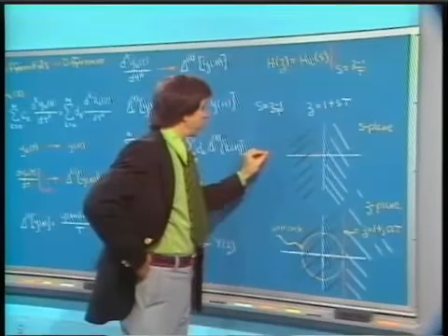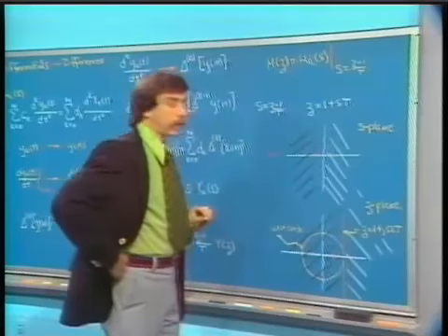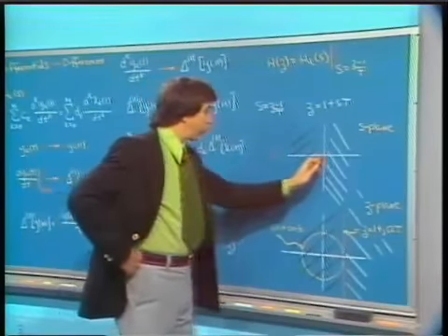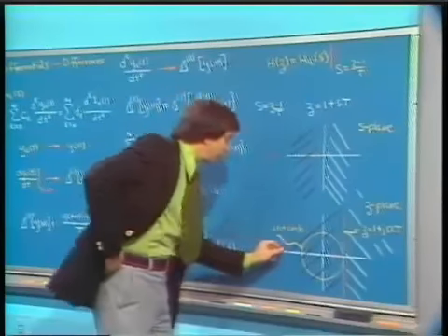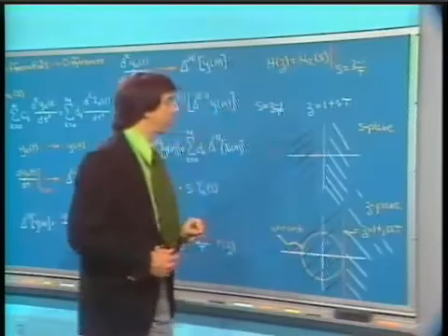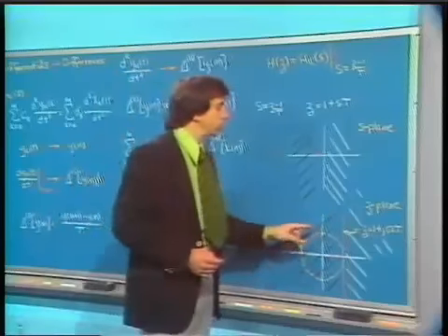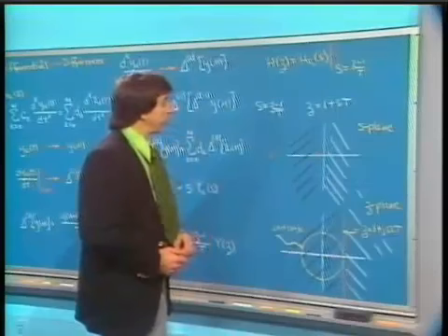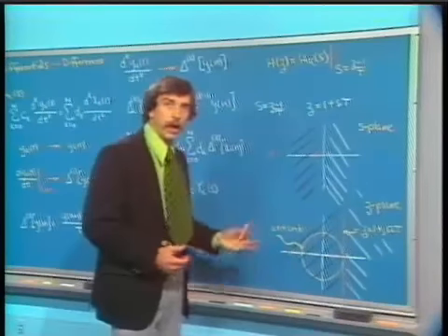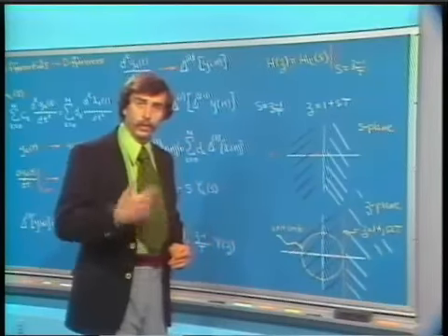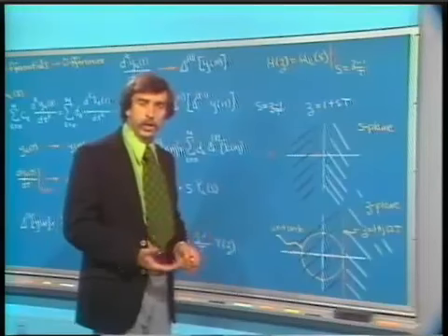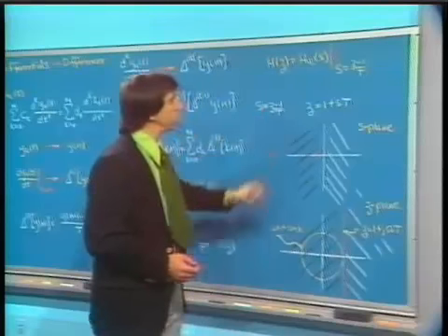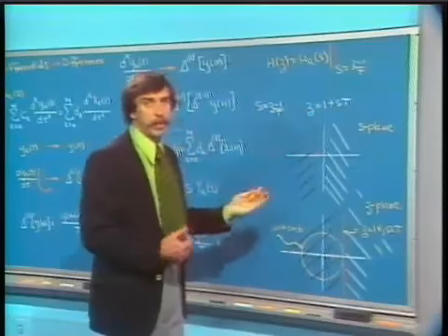However, here's an even more stable analog filter. And if this pole is far enough, is negative enough, then in fact it falls outside the unit circle in the z-plane, and consequently the digital filter will be unstable. That, incidentally, is a well-known property in numerical analysis of forward differences. That is the notion that forward differences are unstable. And this is one way of seeing that, by interpreting it in terms of a mapping from the s-plane to the z-plane.